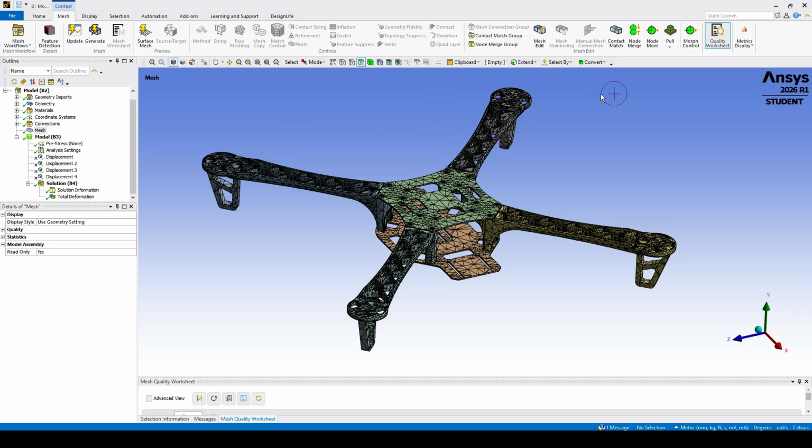Of course, we are talking here about a drone, which should be flying in the air. So if we define a support, even if it's not so rigid, even if it's deformable, at the end it's a support. But in reality, the drone in the air is more flexible. It's near to having no support. That's why in my study here, as you can see, I already suppressed my displacement, so I have no support in my structure.